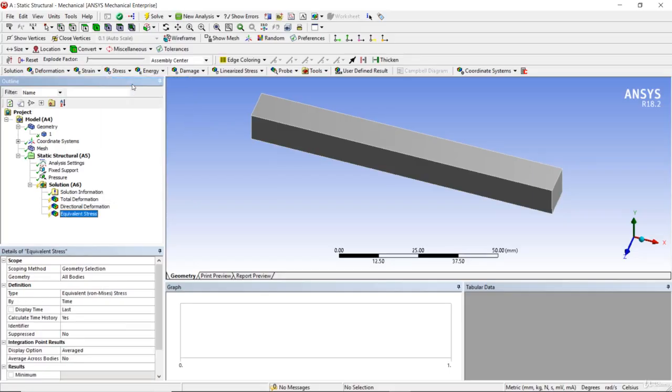And remember, Ansys Mechanical can support lots of types of analysis, like modal analysis, advanced dynamic analysis, transient analysis, fatigue analysis, and lots of other nonlinear analysis. Depending on the type of analysis, the results you can find will vary. Here you are only performing a linear static structural analysis, so you will get only some types of results. But if you change the type of analysis to dynamic analysis, the number of solution options available will change.